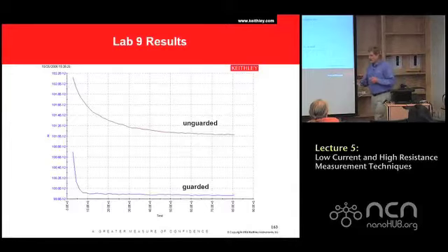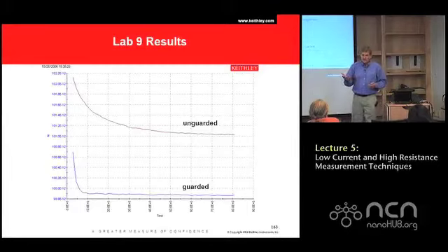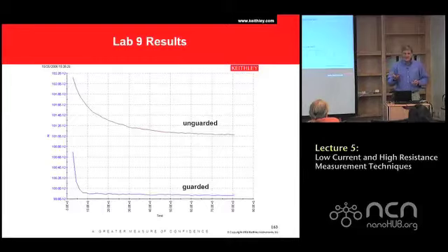You're not always going to have the luxury of using a state-of-the-art system like the Keithley 4200. In some cases, you may have other instrumentation, maybe some older source measure units. That step function test will tell you the quality all the way through your probe system.